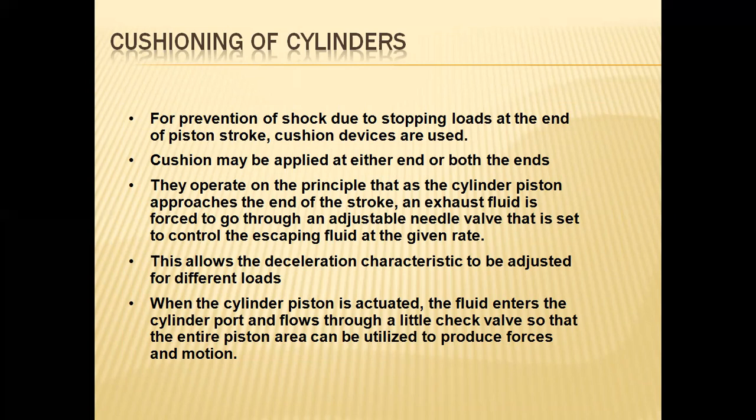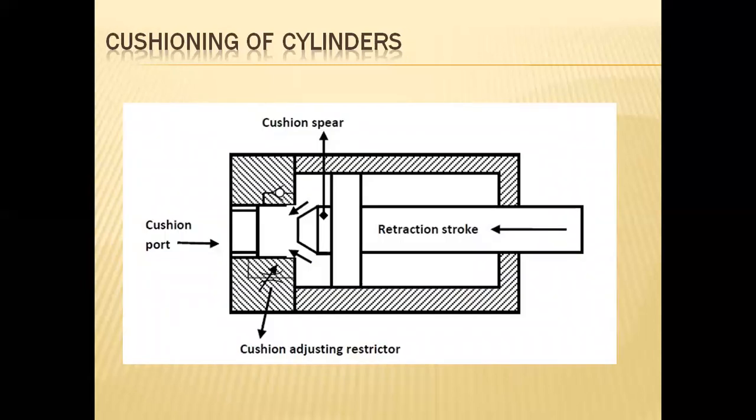And this allows the deceleration characteristics to adjust to different loads. One thing is that when the cylinder piston is actuated, the fluid enters the cylinder port and closes the little check valve so that the entire piston area can be utilized to produce the forces in motion. Hence, this is the condition.